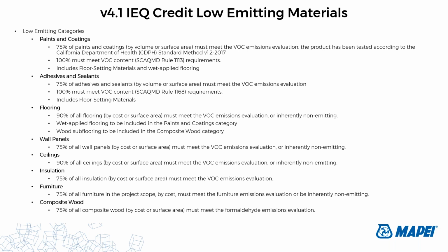And the last category I'll spend time on today is the adhesives and sealants category, very similar to paints and coatings. 75% of sealants and adhesives, including flooring adhesives and sealants, must comply with VOC content requirements under SCAQMD Rule 1168 and provide proof of CDPH compliance.